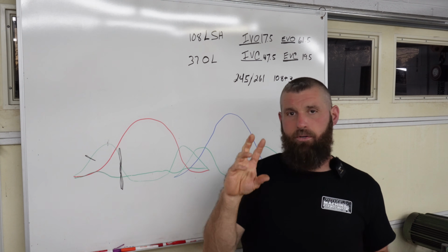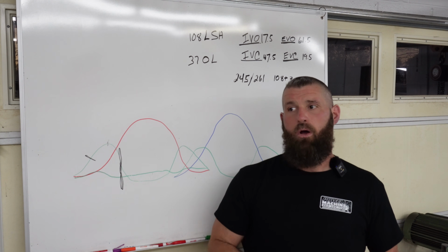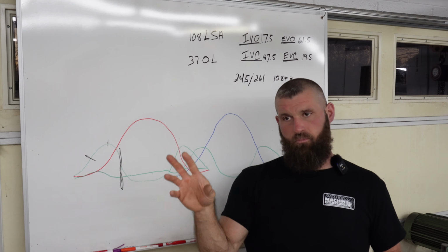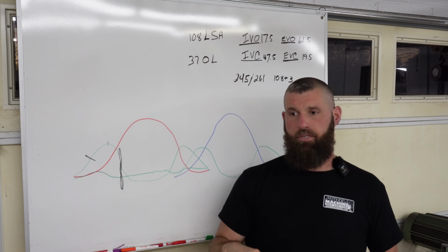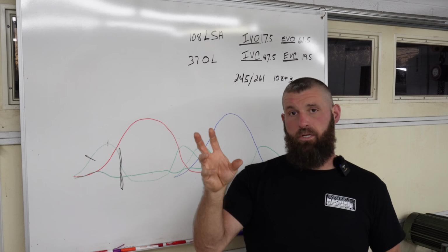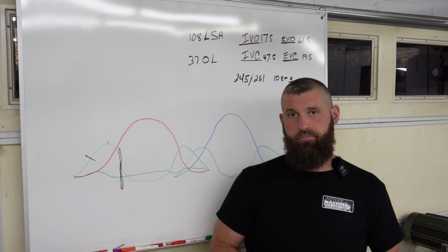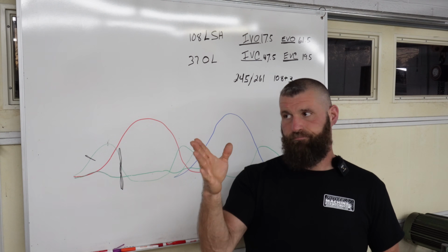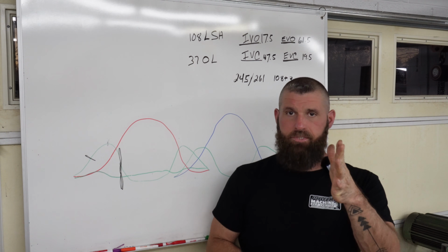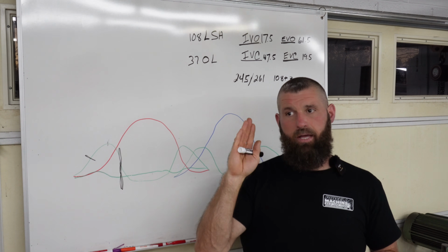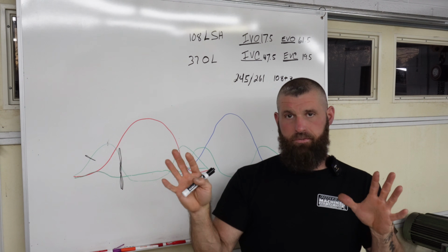So most of the formulas work around that, developed by other people that are smarter than me. Like 240 degrees at 50 is the goal, right? So we need this much cylinder head at 240 degrees to do the job.